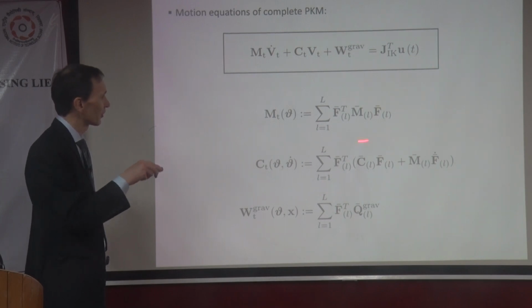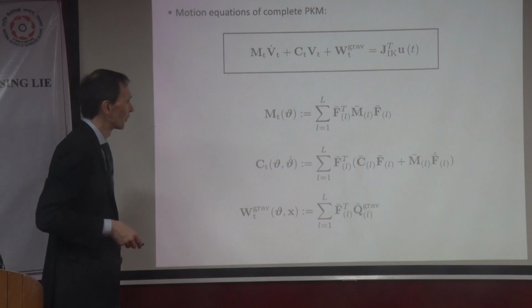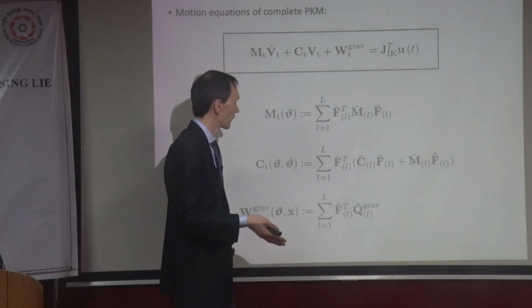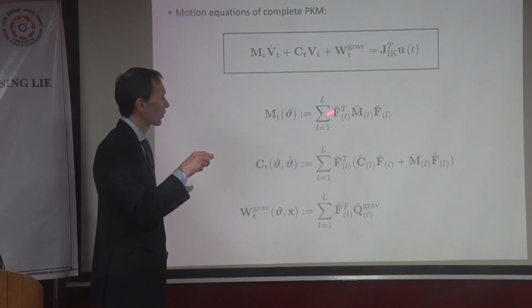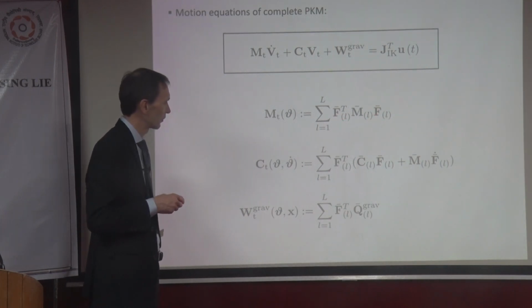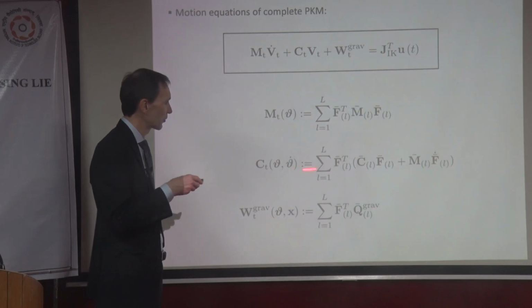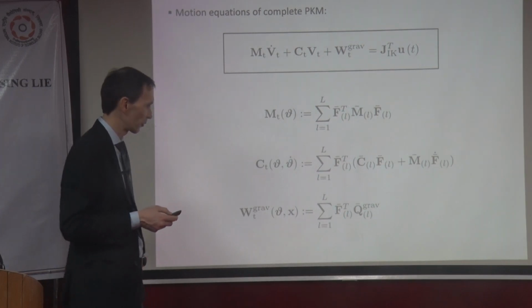And of course we have this form here again, which is again a generalized mass matrix. Okay, it is of course symmetric, and it is also positive definite. And then you have these terms here, they look all the same structurally as we had it before.